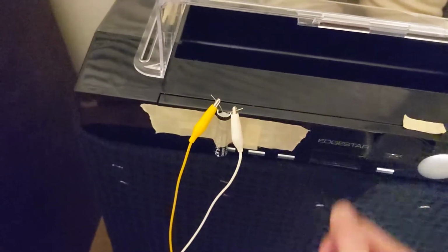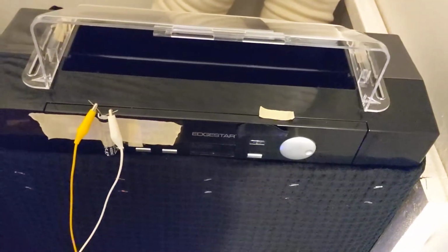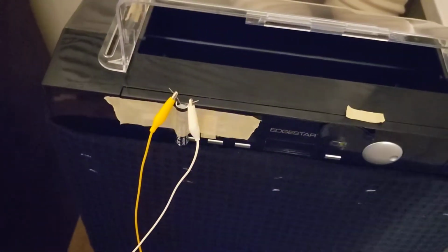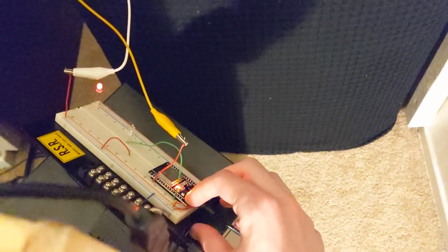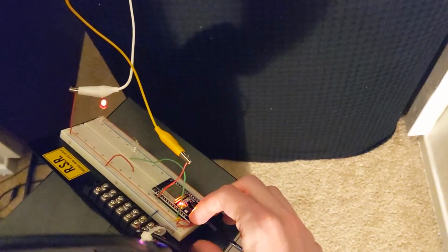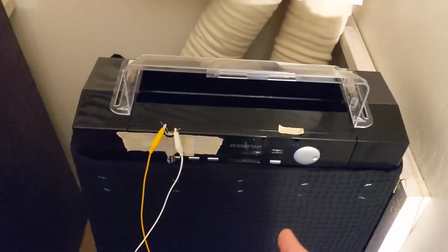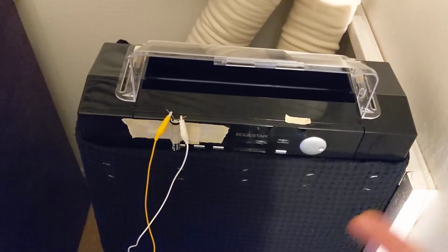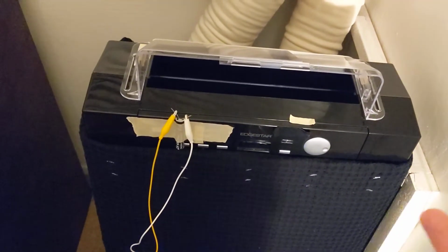the photodiode. Basically what's happening is the ESP32 is going to be sending mode commands, or mode and power, to the air conditioner, and then watching the photodiode to figure out what mode it's actually in. So far I've made this calibration procedure. So I'm going to start it up. It's going to figure out whether the air conditioner is on or off, and then cycle through the modes like 5 times and figure out, oh, this one's cool because it's the brightest.